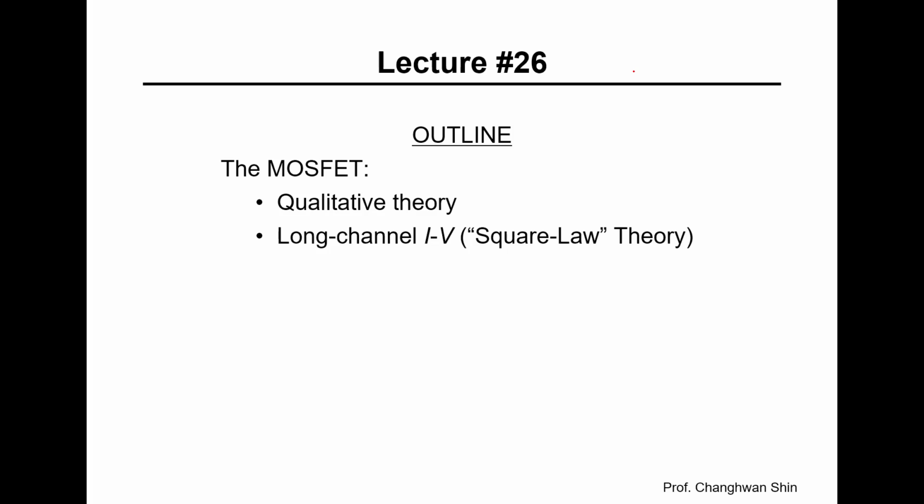So we will explore how voltage applied to the gate affects current flow through the channel, and how the relationship between drain current and drain source voltage defines different operating regions, such as saturation region, linear region, and so on. So the qualitative theory will give you an intuitive understanding of MOSFET behavior, while the mathematical square law model will provide the quantitative predictions.